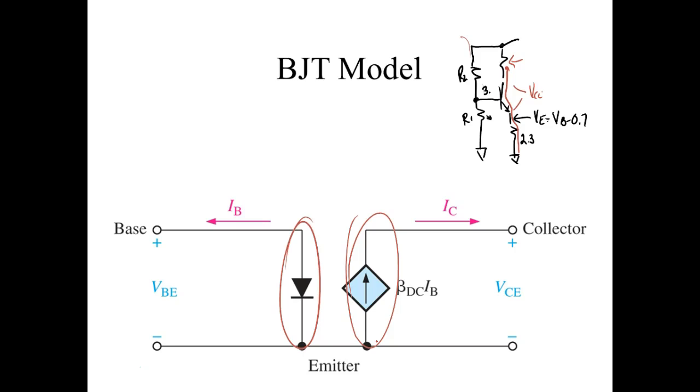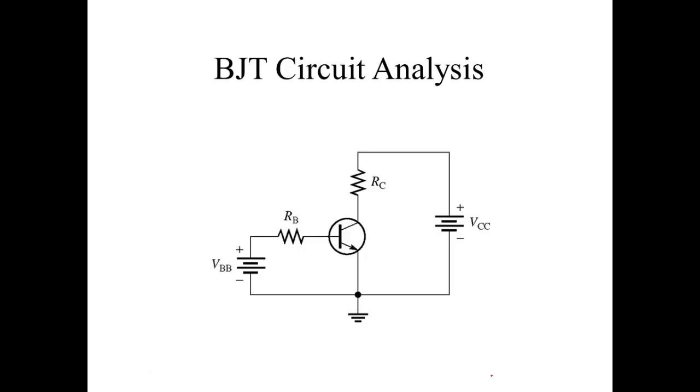We treat them like two different series circuits. They're actually series parallel, but all we do is work on them like two series circuits. And now you got the math. We usually use the voltage divider formula over here because we don't need to know the voltage across that guy. All we need to know is the voltage across R1. Calculate the voltage across R1, subtract 7/10 of a volt across it. That'll give you the voltage on VE. That would be the answer.